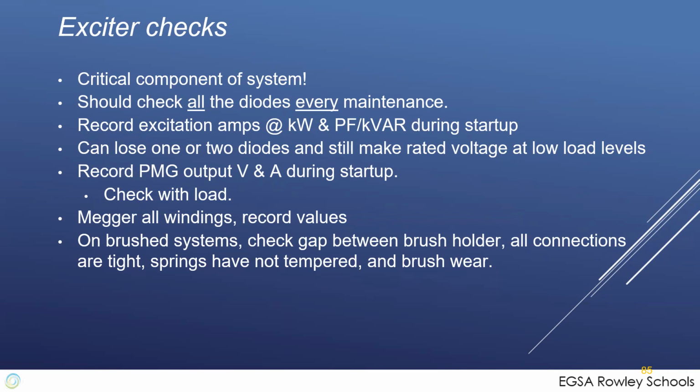On brush systems, you check the brush wear. This is where you get your fish scale out, get your boss to buy you a fish scale. You put the paper between the brush and the slip ring, and you put your fish scale on the pigtails and pull slowly until the paper falls out. It tells you how much force the spring is applying to the brush on the slip ring. I don't suppose you have many slip rings out there. If you want to talk more about that, get me a ring. I'll walk you through that process.